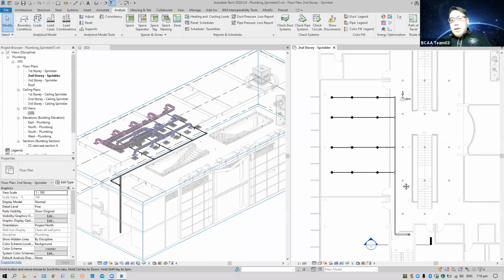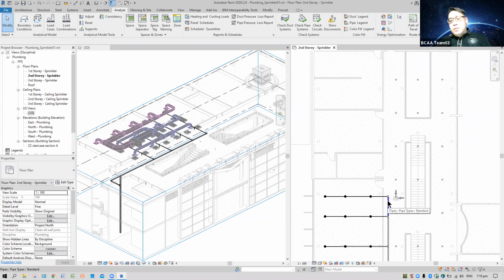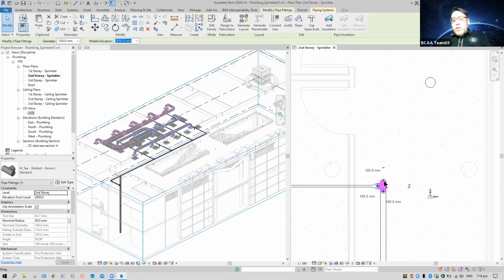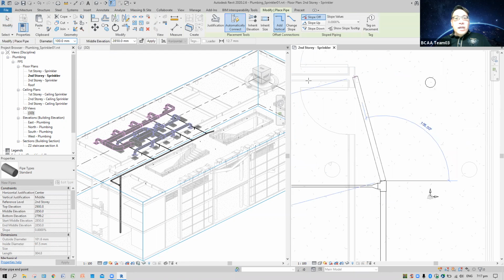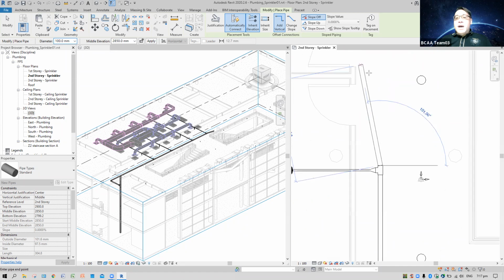So for here, let's say the rest of the room, I can still maintain 100, or maybe I'll reduce one size, which is 90. So to reduce it, you simply select the point and right click. Normally, I think people, their bosses, never mind, all the way 100. So you can say draw pipe 100. But again, I always kiasu, although the height is correct, I just want to play safe. At least inherit all the way, same height.